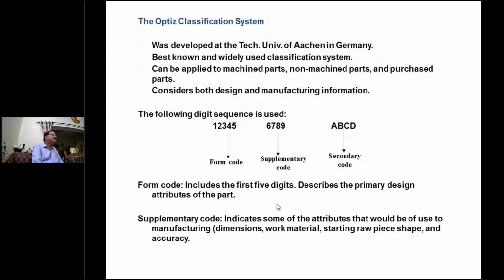In the line layout, your product variety will be very small, but the production volume will be very high. In contrast, in jobbing shop industries, the layout is planned as a process layout. In the process layout, similar machines are grouped together, so there will be one lathe department, one milling department like this.